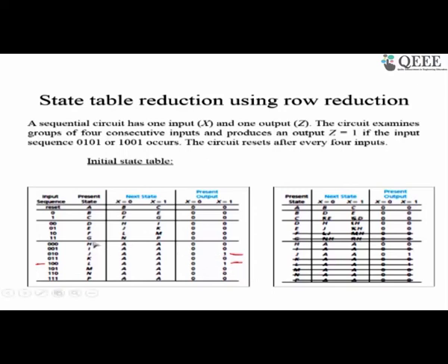So here if you look at H and I, on getting 0 or 1 they go to AA producing the same output. H and I, their pattern is the same. So you don't need separate states H and I, they can be the same state. From that you can see that J and K are different, J and L are different, K, M, N, P are all identical. So instead of this you can retain only one state.